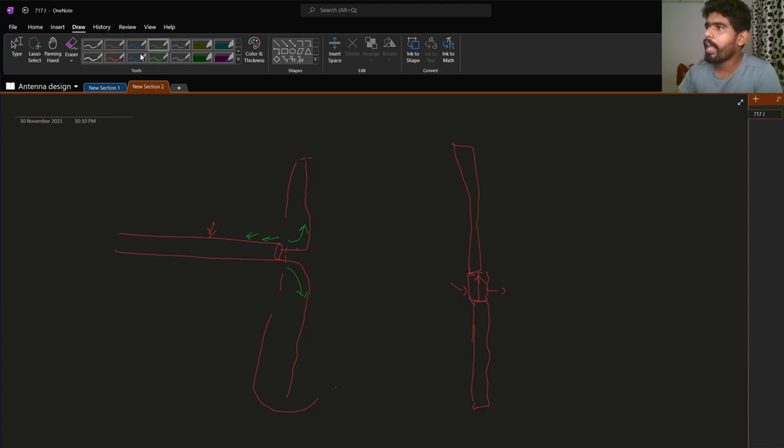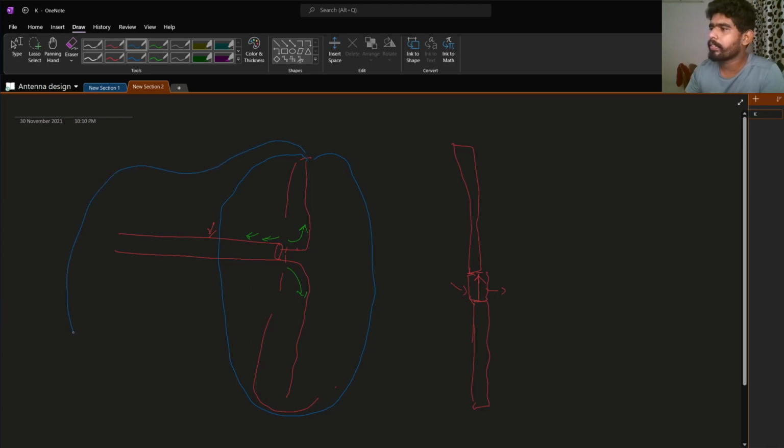The problem is that we expect the radiation pattern to be like this, a perfect radiation pattern, but in the real case the pattern may be distorted like this, because most of the current, or half of the current, may go through the shield, because of the balance issue. So the field is not matching with the field in the antenna, and the radiation pattern is different.